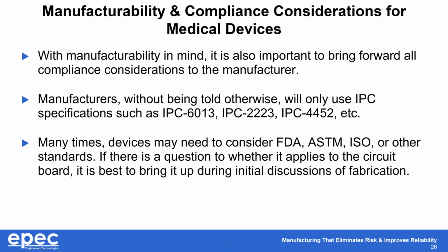So with that in mind, it is also important to bring forward your compliance considerations. What I mean by this is typically we only consider for any design IPC specifications: 6013, which is the standard for flex circuits, 2020, 2223, which is the guideline for flexible circuits, 4452, the ENIG standard, and any standard beyond that among IPC standards.